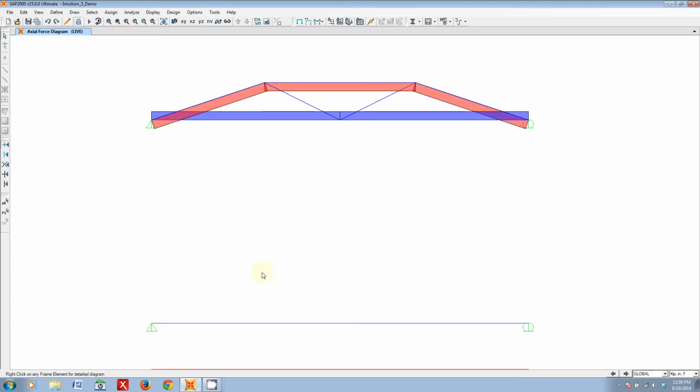Now, same thing with our beam here. Remember, we had a ramp up to a linear constant moment region here, and that's the same thing that I'm doing here. But remember, I technically shouldn't need to include these because there shouldn't be any shear inside of my truss in that region. So effectively these two members carry no force because there's no shear in my truss, but I need them in order to ensure that the truss is stable, because remember, these are pin joints. So if I took these out, the whole top assembly would pretty much flip around and do nonsense.